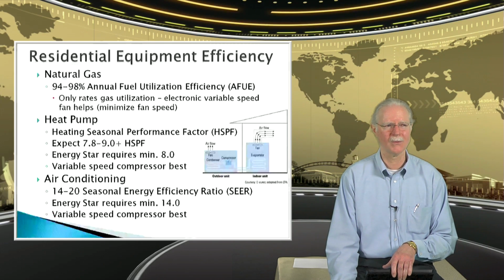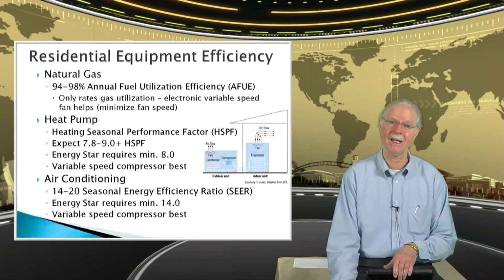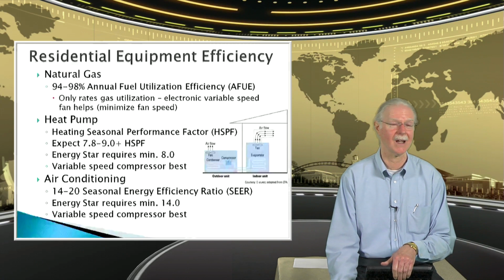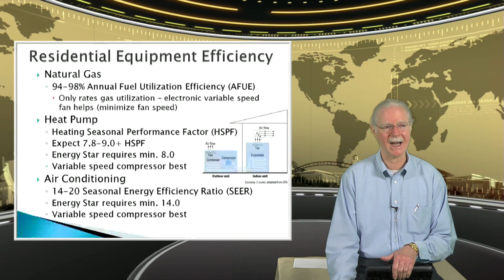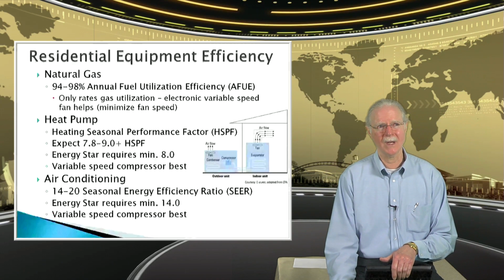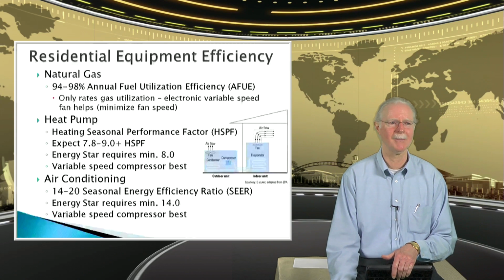With the heat pump, we have a really, really big impact in that the colder it gets, the less heat there is available. So if we're operating in a condition where it operates most of the time at 32 degrees or less, it's not a very efficient system. By the time you get down close to zero, there's not much heat there at all to squeeze out of that outside air.